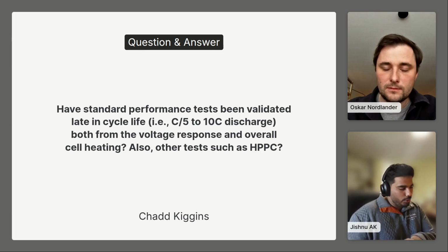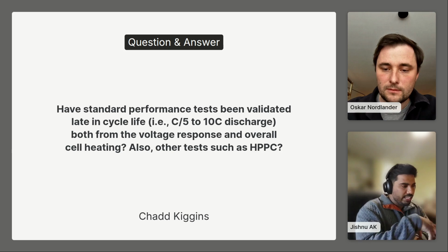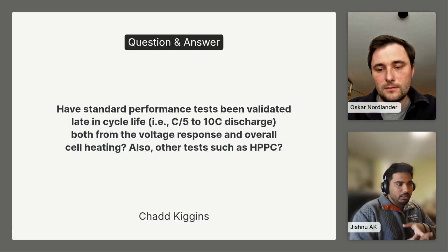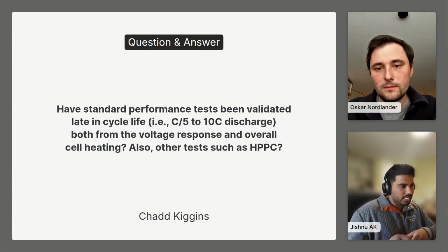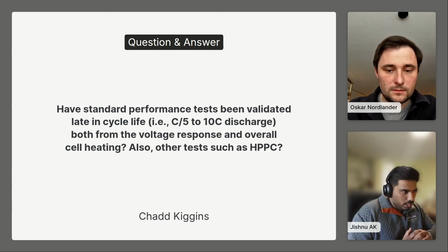The reason we don't do it now is that since the electrochemical model is already validated at beginning of life, what changes in that model are some of the parameters internally. We get proper validation of that by looking at the SOH trajectory as well as the voltage validation that we already do. But of course, this is possible, something we don't do now.